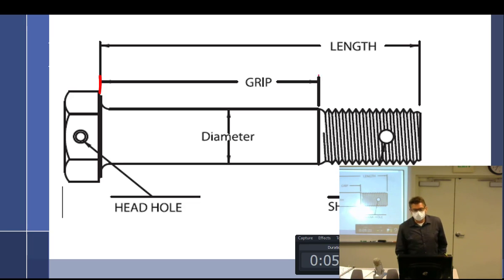So it's going to be in what? What's the length of a rivet? 32nds and then 16ths, okay? And so this is going to be in eighths. And what's the diameter of a rivet? 32nds. This can mean 16ths. So it's just double because they're a lot bigger. So the length is going to be in eighths in nominal.